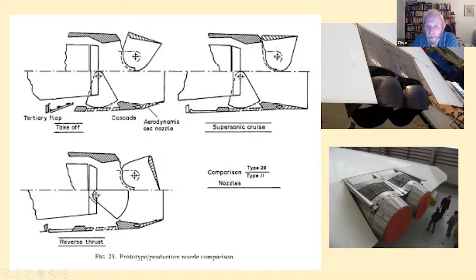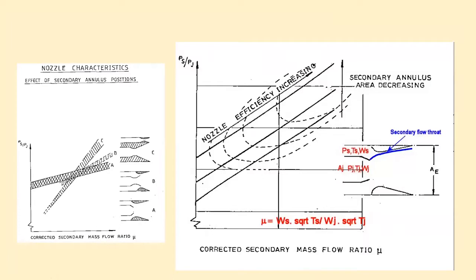There was obviously a bit of a gap there, but it's nothing like what we got from that. And in takeoff or in transonic, subsonic conditions, the ventilation on the nozzle I talked about was obtained by partially deflecting the buckets so we could get ventilation from the inside. A big difference between the two, as you saw from the table earlier.